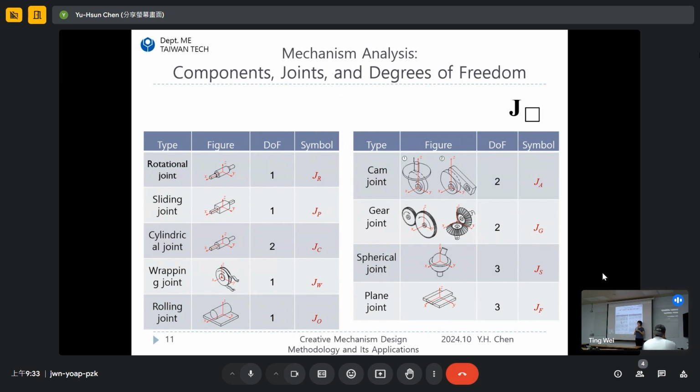That is like the joint of our shoulder, where we can rotate our shoulder to move forward, to move upward, and it can also rotate along the x-axis. So we say that it has 3 degrees of freedom. That is, you can rotate along 3 directions. And how about the revolute joint?